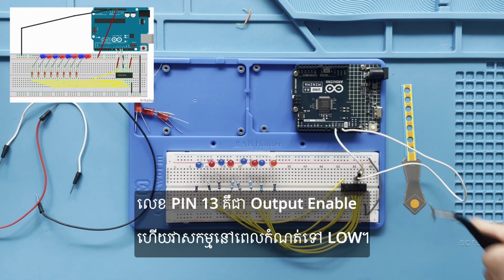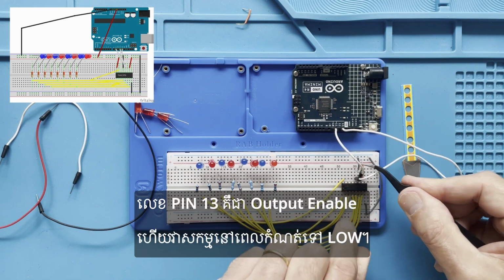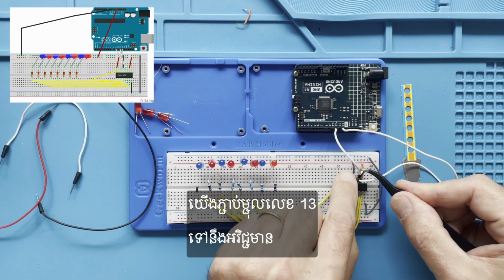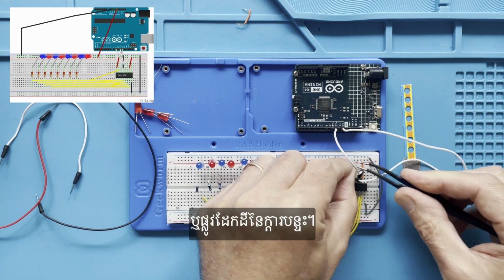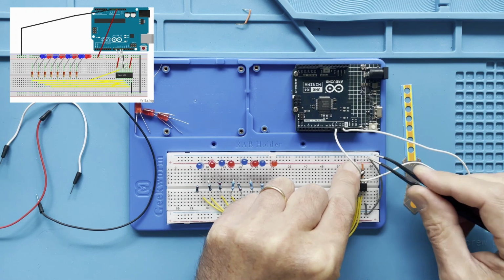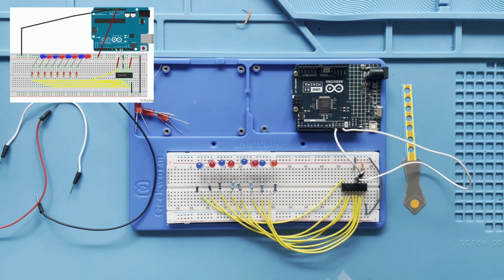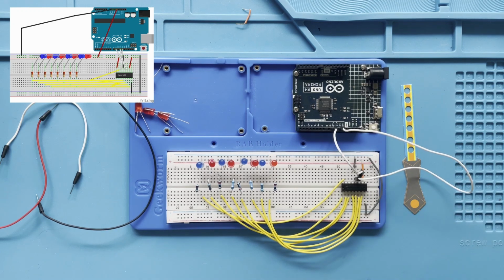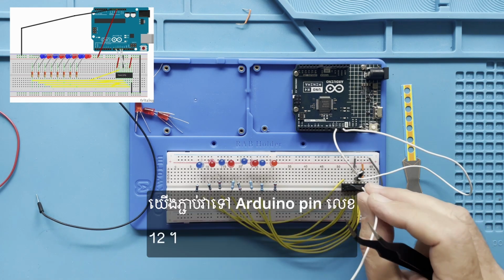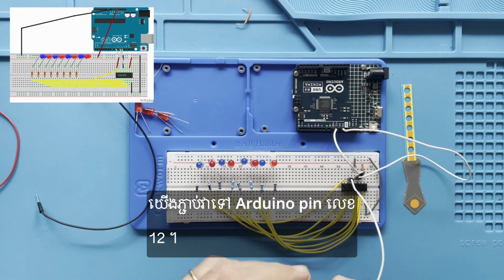Pin number 13 is the output enable, and it is active when set to low. We connect pin 13 to the negative or ground rail of the breadboard. Pin number 14 is the data pin, and we connect this to the Arduino pin number 12.